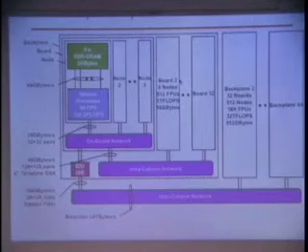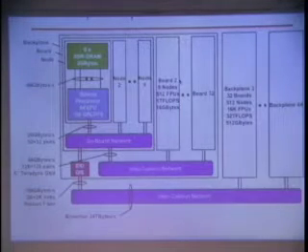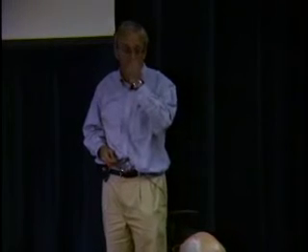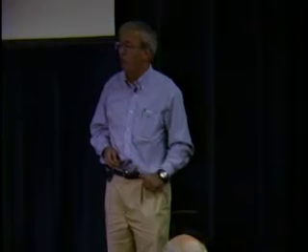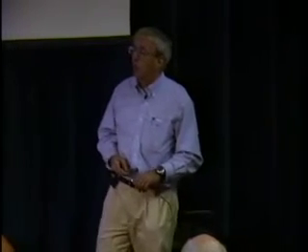What are the differences? Well, instead of having something with 32-bit floating point units, you want something with 64-bit floating point units. So the Merrimac processor is defined with 64-bit floating point multiply-add units, 128 gigaflops per chip. And you want a little bit different memory system.